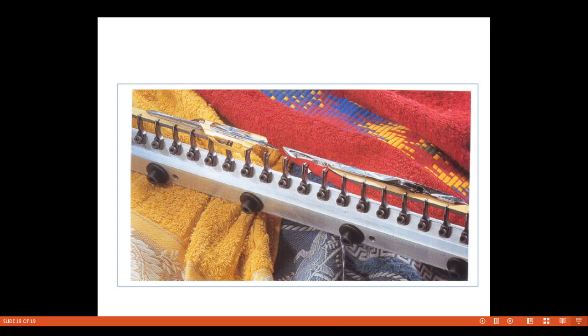But nowadays the guided rapiers are not there. The guides are removed, and the tape width has been increased. So see the sley here, aluminum type of sley. So very less width is there, and the weight is less. As the weight is less, less energy is required for beat up, the forward and backward movement of beat up. Here the reed attachment will be there at the screw. So for the forward and backward movement very less energy is required. That's why the speed of the machine can be increased. This is the added advantage.